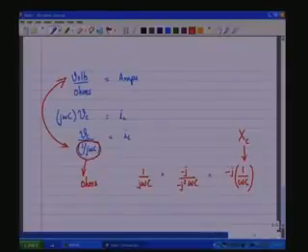And there is a phase shift which is corresponding to this j here, and the minus j, which is a minus 90 degrees rotation in the space vector, which would mean it leads, that is, it occurs before the normal phase vector. So, therefore, this has a leading effect, and here we have capacitive reactance.